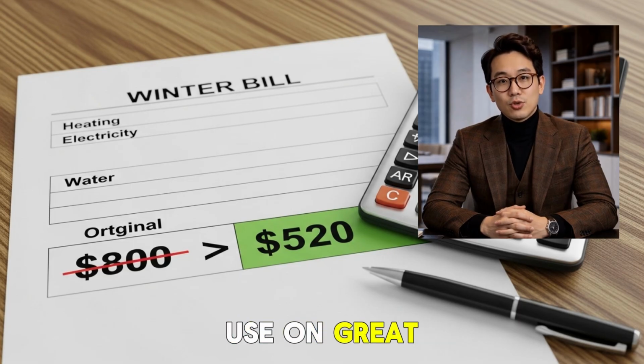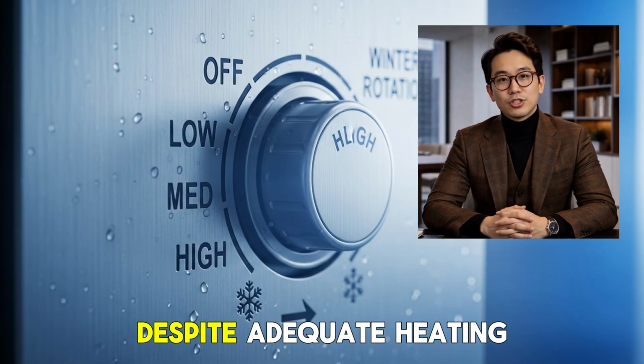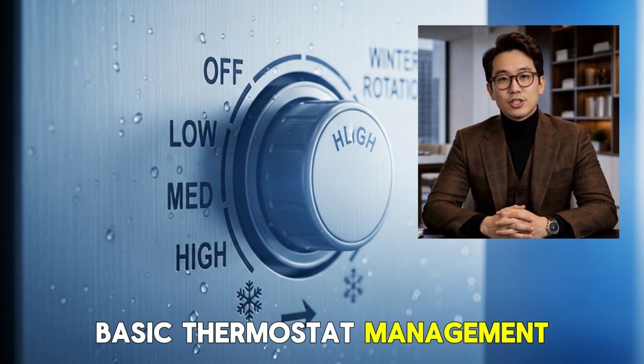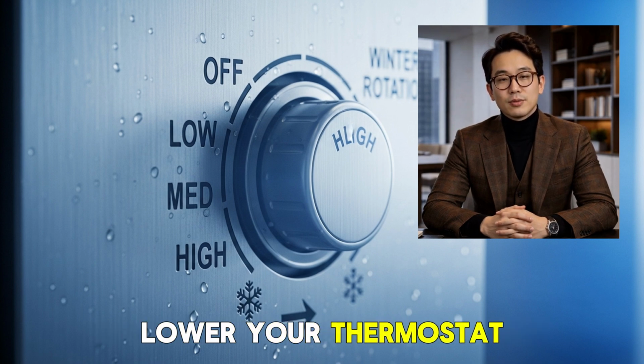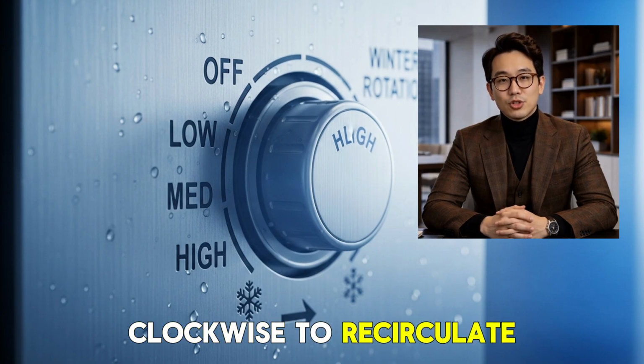Focus winter fan use on great rooms, vaulted ceiling spaces, and any room where you notice cold floors despite adequate heating. Pair ceiling fan winter operation with basic thermostat management and savings multiply. Lower your thermostat 2 degrees from normal winter setting. Use ceiling fans on low clockwise to recirculate warm air.